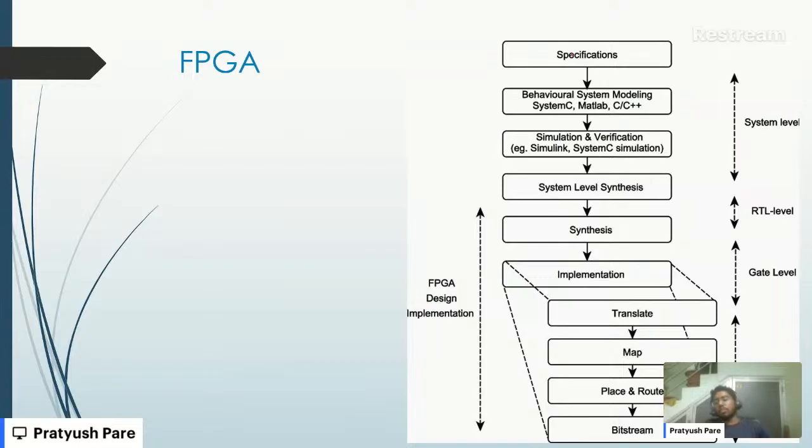So what will Gautam start with? He will have some specifications. It is a GSM IP, and it should support this bandwidth or be fast enough to do these kinds of operations. It should have this area constraint, and consume this much power. I don't want this many logic gates; I have a hard limit of using 100K logic gates or something like that. I don't want to use BRAMs, I want everything in logic. Everything like that will come.